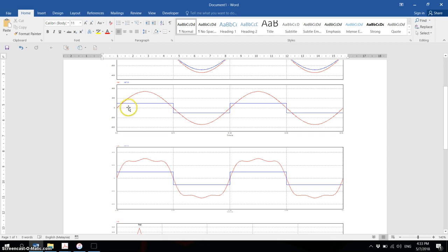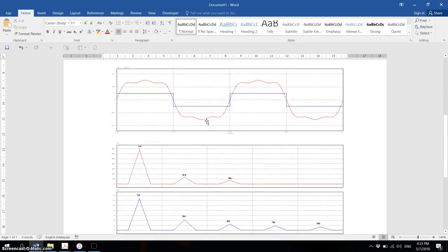For example, in the full wave rectifier we sometimes have a square waveform, and we also looked at the three-phase six-pulse rectifier, where the current is a quasi-square waveform. Also, when we talk about AC voltage controllers, we might have a non-sinusoidal supply voltage, and the current is, for example, a square waveform current. So how can we calculate the actual power from it?